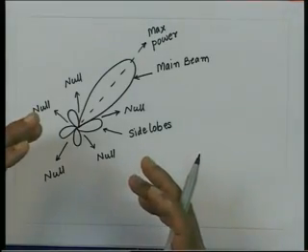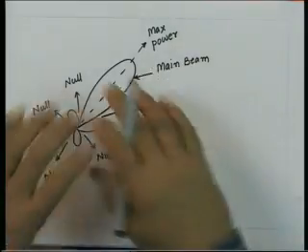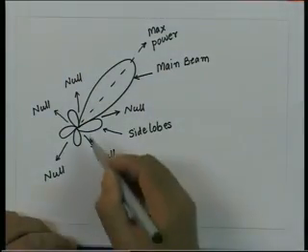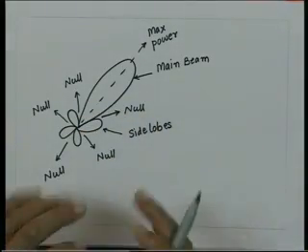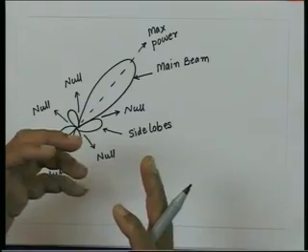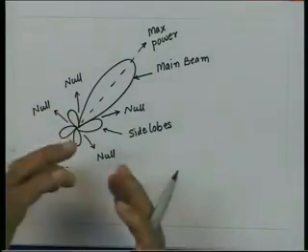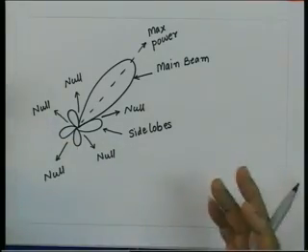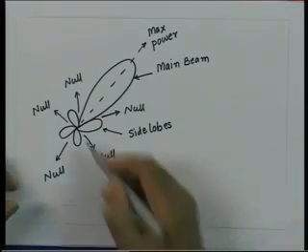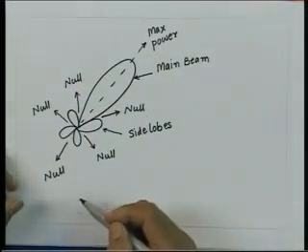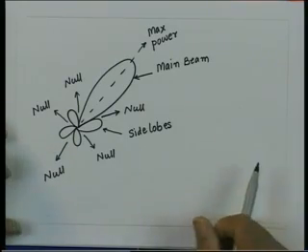Whereas, if I want to use the antenna for broadcasting application, then this beam should be as wide as possible, and there should not be these zones where the nulls are there. So, depending upon the application, I have a variety of requirements for the radiation pattern. In some cases I will require a narrow beam, in other cases a very wide beam and no nulls, because in broadcasting applications the nulls are not desirable: in those sectors there will not be any radiation and there will not be any reception of the electromagnetic wave.